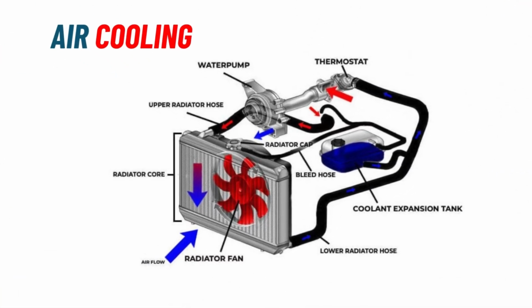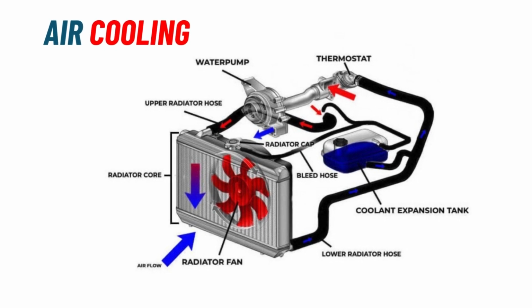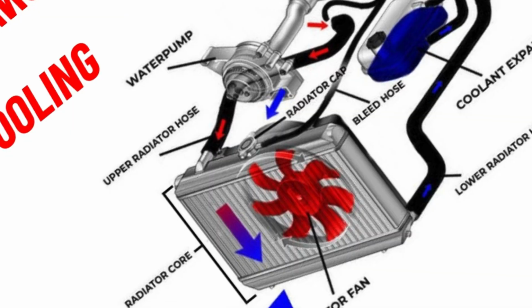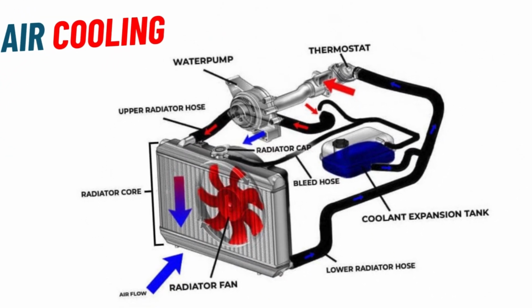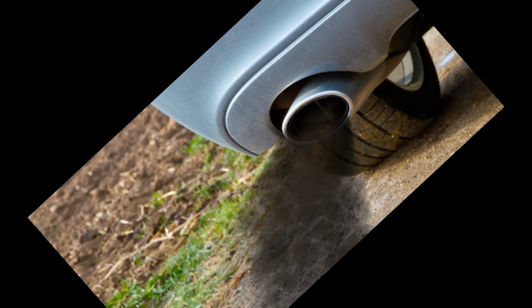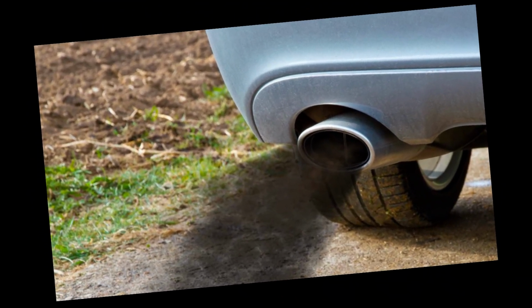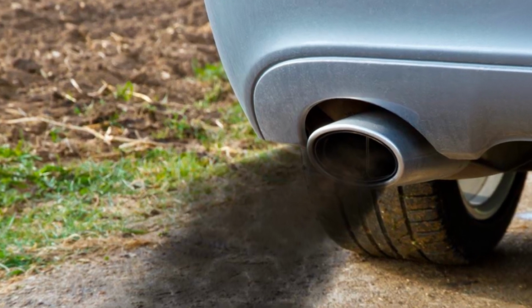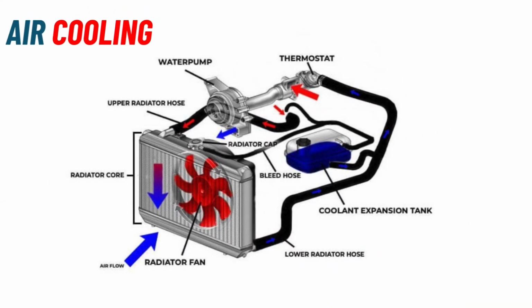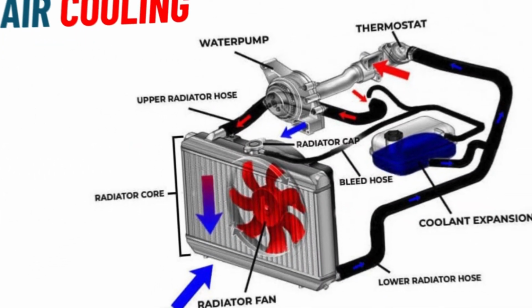Airflow over the radiator, either through the vehicle's movement or electric fans, carries heat away from the radiator's fins. This process cools the coolant inside the radiator, lowering its temperature. These processes work together to maintain the engine's temperature within the optimal range, ensuring efficient combustion, reducing emissions, and preserving the longevity of engine components. Effective temperature regulation and a well-functioning cooling cycle are essential for the overall performance and reliability of the vehicle.